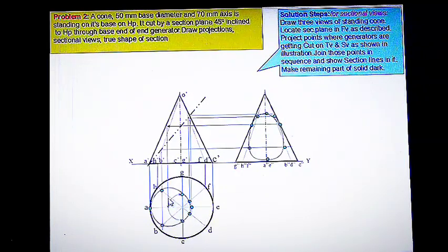Okay, now this obtained point, similarly we will get the intersecting points on the plan by drawing the vertical projectors in the downward direction. We will get the intersecting points on this OB, OA, A dash. This is the intersecting point in the elevation. Corresponding point will be at point A in the plan.